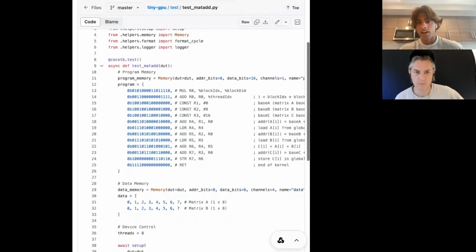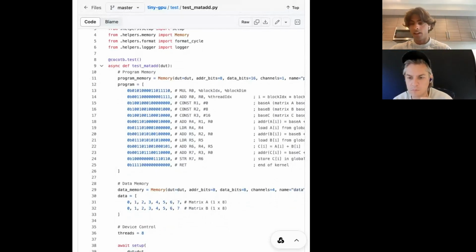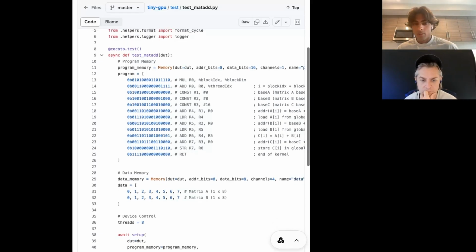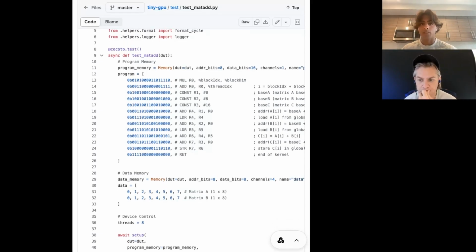And then in Python, I wrote this external interface, since the memory is external to the GPU design. It's not in the hardware. So I made a simulator right there that simulates exactly the behavior of memory. On every cycle, it checks if there's a request to the memory from the memory controllers, and if there is, it responds with the data. The reason is that memory is not part of the GPU. It's usually an external DRAM or high bandwidth memory or something like that, so you wouldn't include that as part of the design. So that's what we're simulating here.